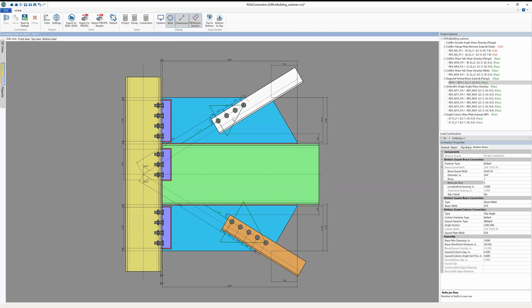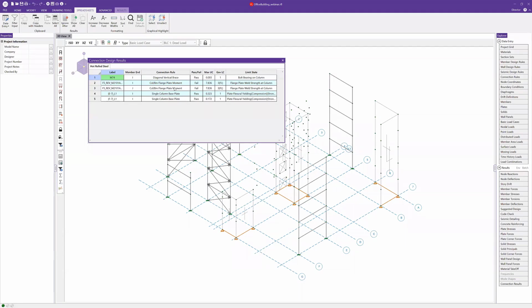And so once we're done, again, we want to have this confluence of everything that we're doing. We can use this export to Risa 3D button and send this back into Risa 3D. So I'm just going to choose export here. We'll export back into Risa 3D, and if I open Risa 3D now, it's telling me, hey, I didn't solve everything, right? I didn't solve my problems with my flange plate moment connections, but it's telling me that really my weld strength is the worst case.